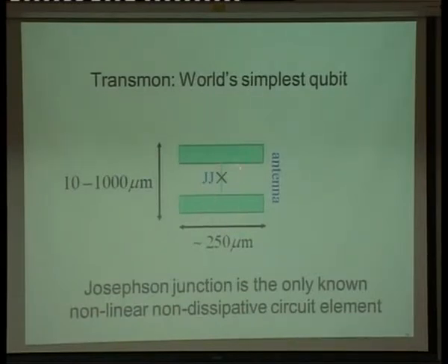So we do that by introducing a Josephson tunnel junction, which acts at some level of approximation as an inductor, a large inductor connecting the two sides of an antenna. But it's a sort of nonlinear inductor and produces an anharmonic oscillator whose two lowest levels can serve as an artificial atom. And you can design the size and shape any way you want. The current version that we use is about 1 millimeter long. You can see it with your naked eye.